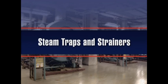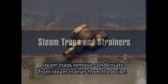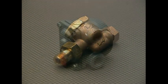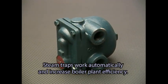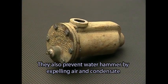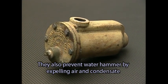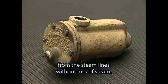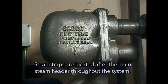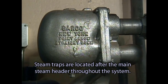Steam traps and strainers. Steam traps remove condensate from steam in lines from the boiler. Steam traps work automatically and increase boiler plant efficiency. They also prevent water hammer by expelling air and condensate from the steam lines without loss of steam. Steam traps are located after the main steam header throughout the system.